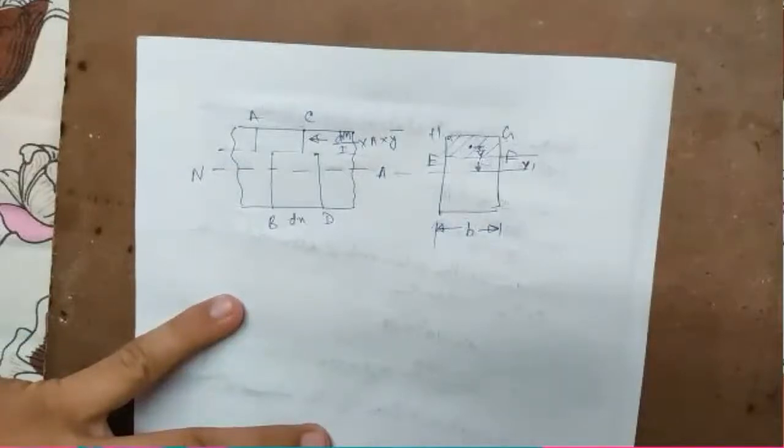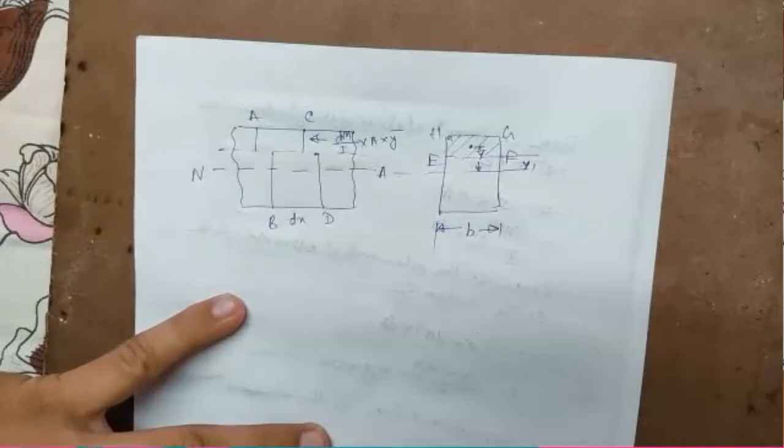Hence, in order that the above part may not fail by shear, the horizontal section of the beam at the level EF must offer a shear resistance. The material should offer a shear resistance against this shear force, and this shear resistance must at least be equal to the unbalanced force to avoid failure due to shear. Otherwise shear failure will occur.